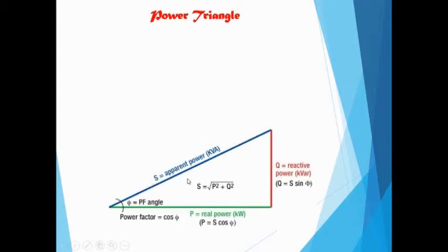Q is the reactive power, and it is on the y-axis rather than the x-axis because it's the reactive power. It's the power that you're not using, you're returning it in fact to the supplier. But if you're not taking that into consideration in your industry, or at home, then you might end up paying a lot more for what you're using. So that leads to this power, which is apparent power, S, which is the combined real power P and reactive power.